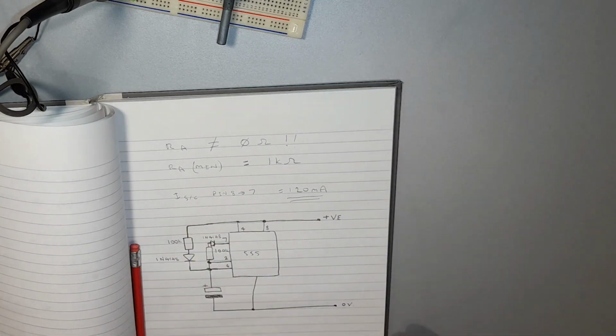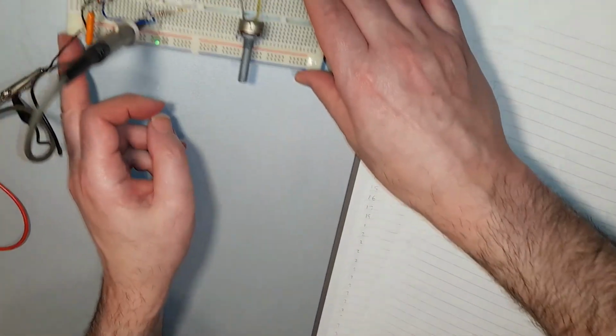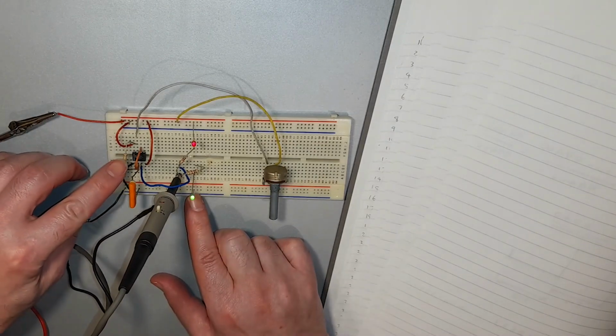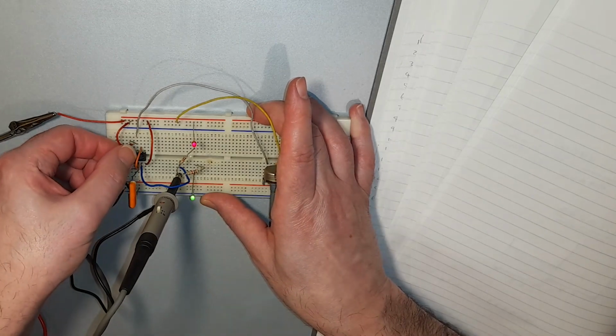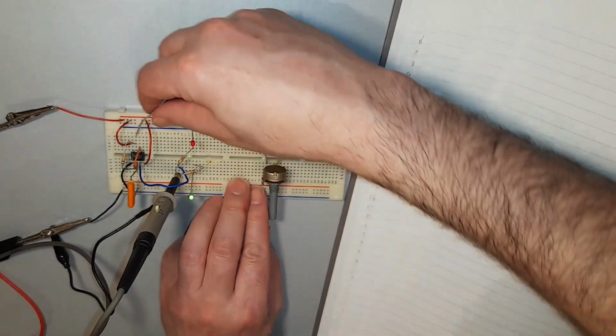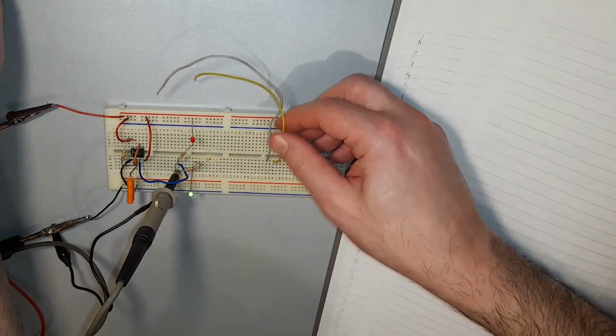Right, and we're going to keep the circuit live while we're doing it. Okay, so we've got one resistor here, but it needs to come to a separate point here. So from positive, sorry, that's this one here. I'll take this out. And we need a 100 kilo ohm resistor.